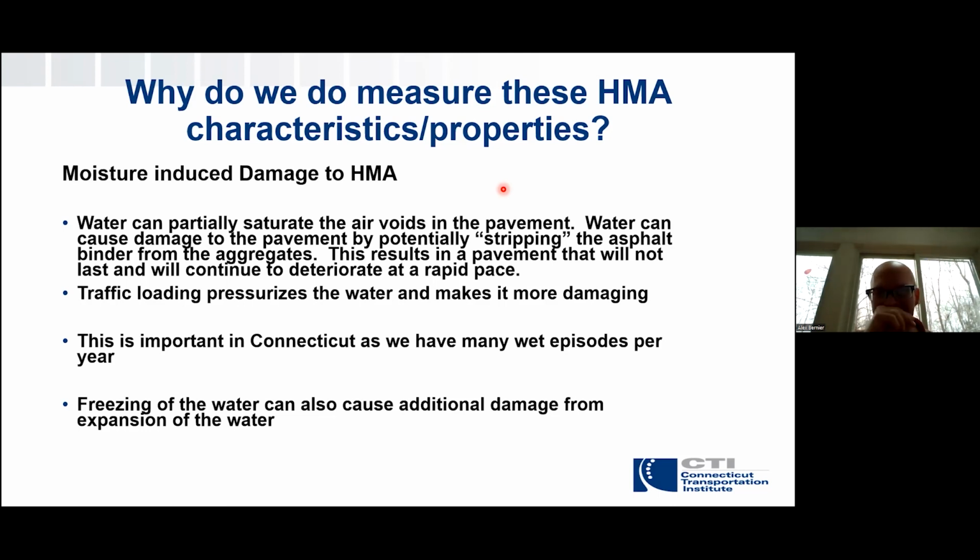A good example of this, and actually an example most of us live through in the Northeast, is people with radon fans in their basements, right? This is an example of aggregate that is reactive. It's changing its properties as we're exposing it to our environment, right? So we're talking about bedrock that was buried for a long time. We bring it up to the surface and we're going to build with it or do something in and around it. That's going to affect these unstable aggregate. And it's not unstable in the sense that it's going to fall apart. What I'm talking about is chemically, where it's actually going to change.